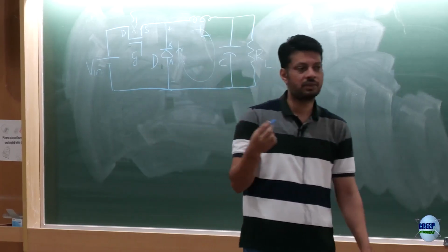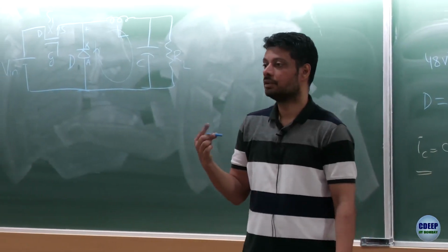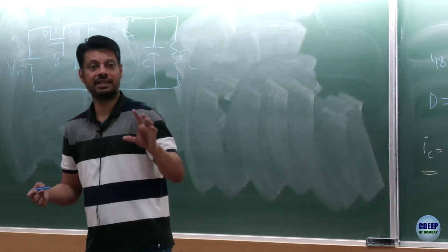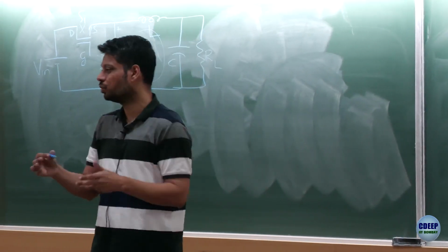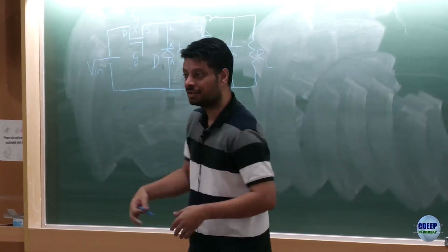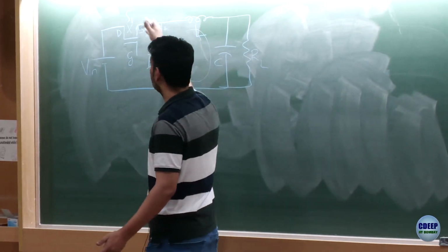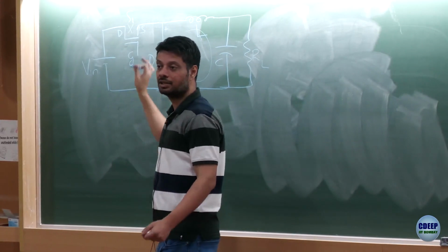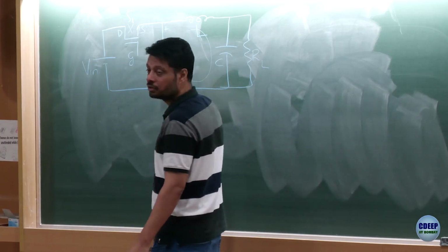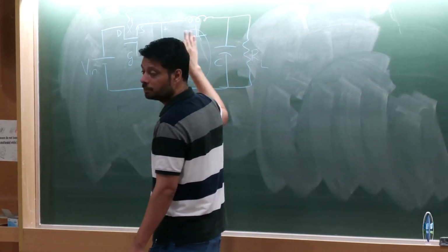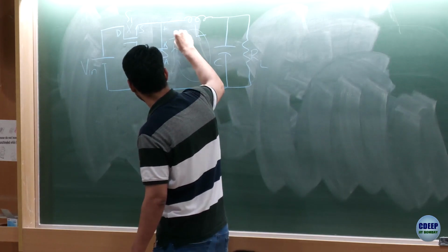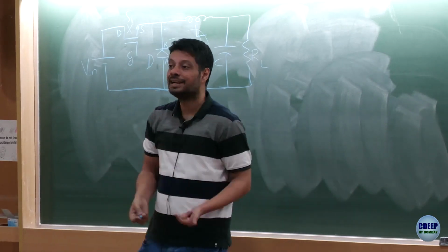This is something which we discussed in the first class. Do you guys remember anyone? No? So this was my question: the diode gets turned on because of voltage or current, right? Usually we say positive voltage will turn it on, but here we are saying that because of the current, because this current doesn't have any path, it will turn on, but that's ridiculous. How would the diode know that there is no path for the current? Imagine if this diode does not turn on, this inductor current would suddenly become 0, so di/dt would be infinite, and it would force a polarity of voltage like this on the diode, and that means the diode will turn on.